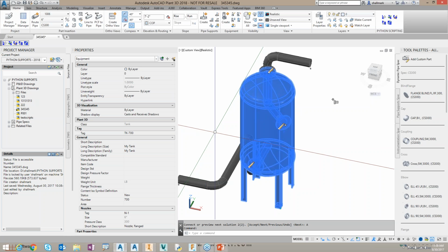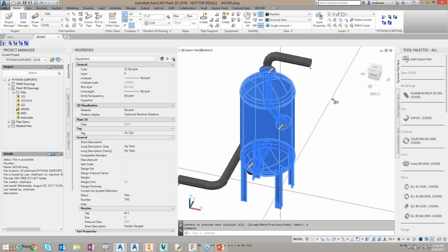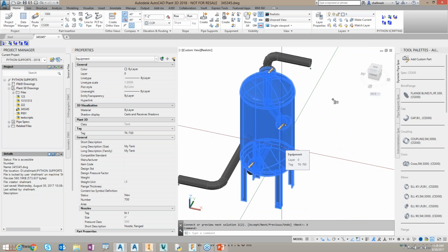When we import that new model, it's a new model in there. But by having the box as the equipment, that's the only thing that stays consistent. It doesn't change. We just import the new geometry over that, attach it to the box, and then update any nozzle locations.